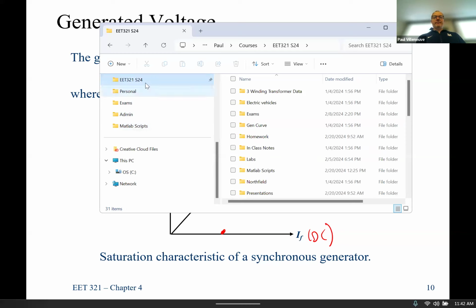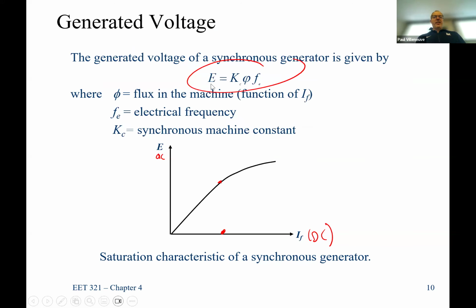and you're going to get a rotational voltage that way. And then how is it connected? How is it related to the DC on the circuit? This right here, yeah, right here. This flux right here is because of the amount of field current. The more DC current you have, the more flux you're going to get in that rotor circuit, which is going to allow you to control the voltage.